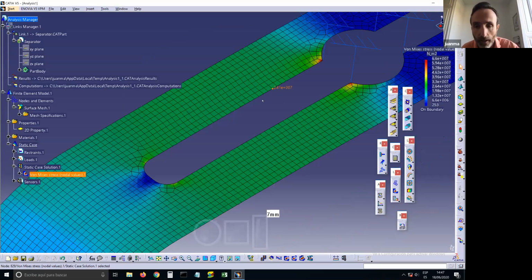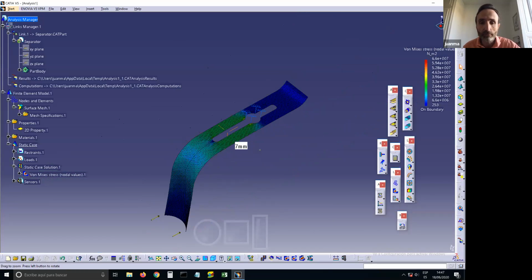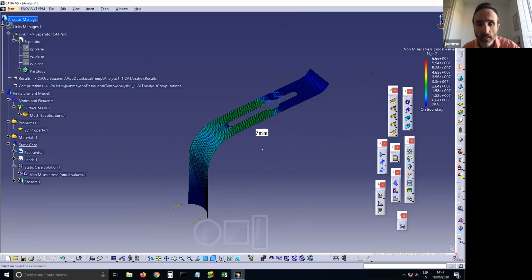That is allowable, okay? When we get closer to the corner, the stresses will increase very quickly, but you see that the stress very close to the hole or to the corner is still allowable. So that means that we don't have to worry so much about this stress concentrator. Okay. So now perhaps we can decide that this is a correct design with increased thickness for a plastic part.